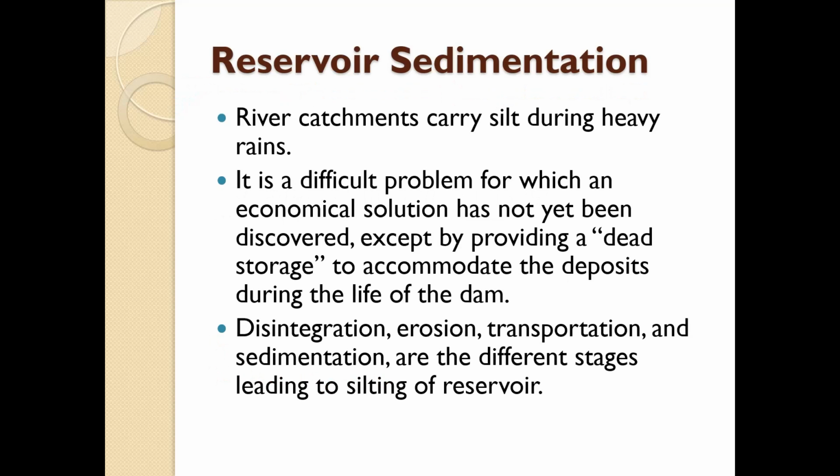So to begin with, reservoir sedimentation. Every year, a river carries a certain amount of sediment load. The sediment particles try to settle down to the river bottom due to gravitational force, but may be kept in suspension due to upward currents in the turbulent flow, which may overcome the gravity force. Due to these reasons, the river carries the fine sediment in suspension as suspended load and larger solids along the river bed as the bed load.